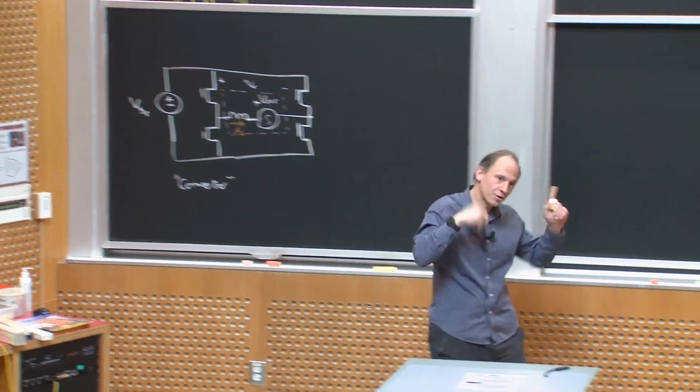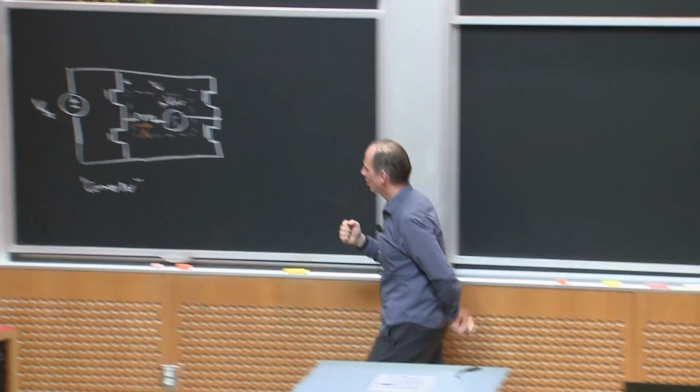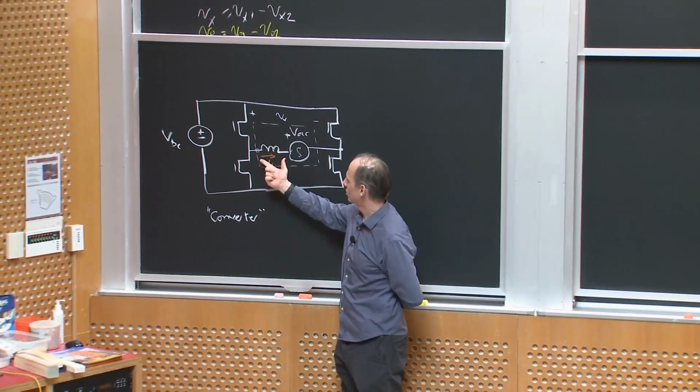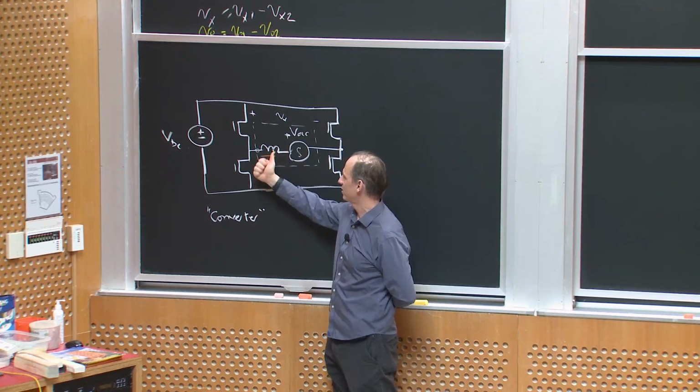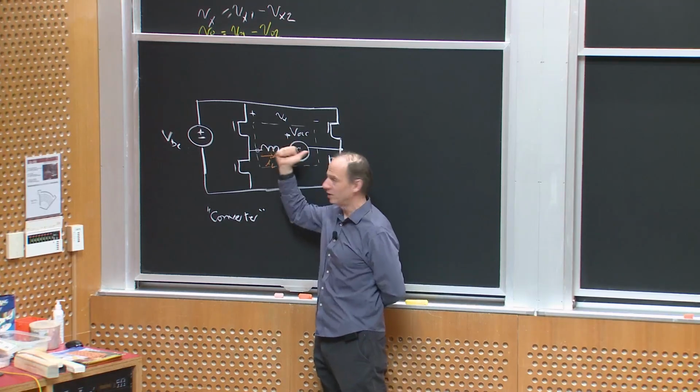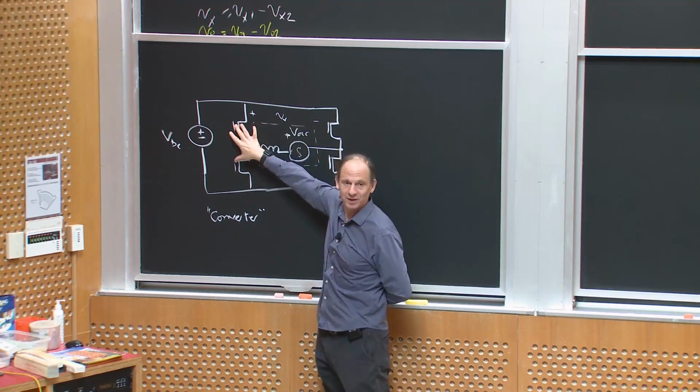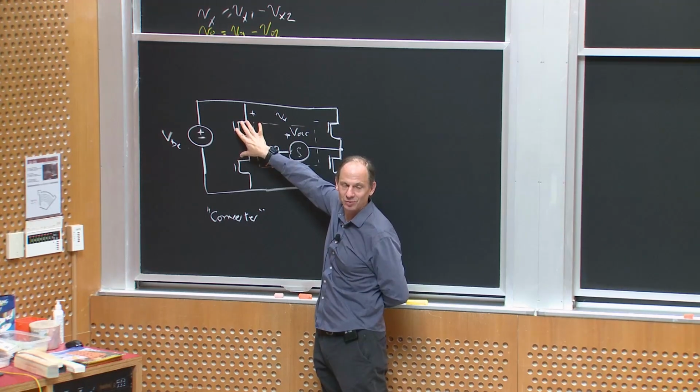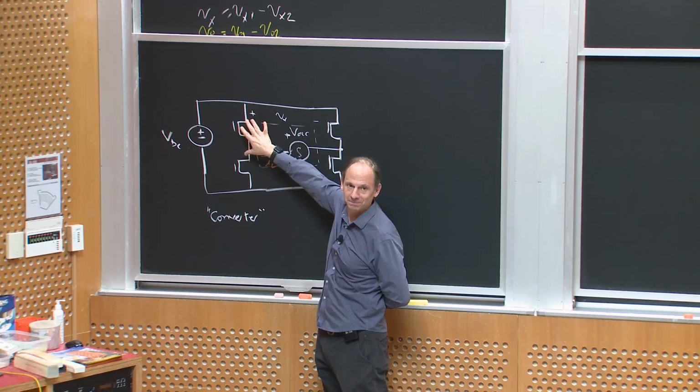Now, if I had a current source inverter, here I'm talking about deciding power flow direction based on the sign of this current, where the voltages I apply are the same sign. If I had a current source inverter, I'd do the reverse. The current would have the same direction, and I'd do it at a different voltage polarity.